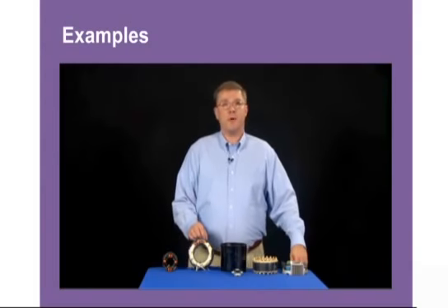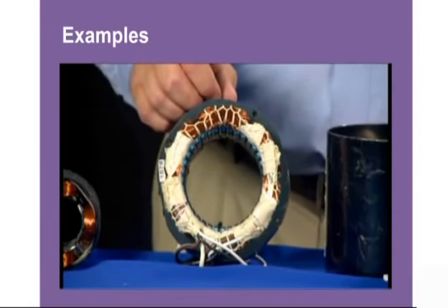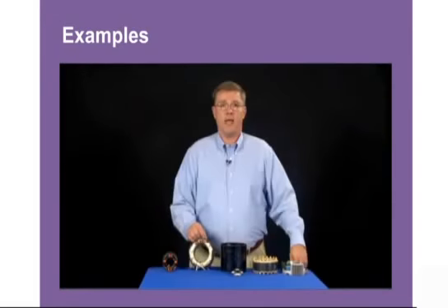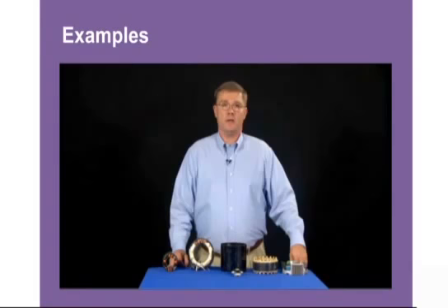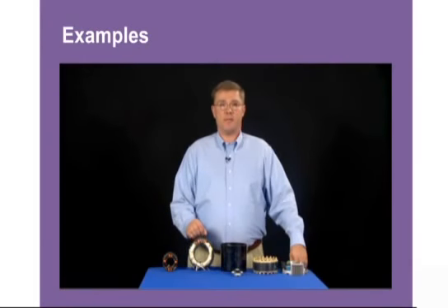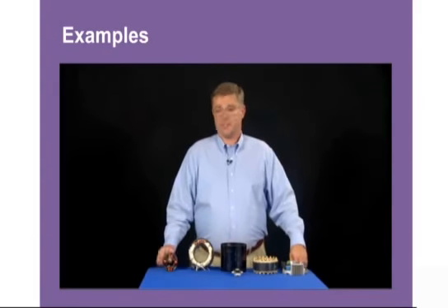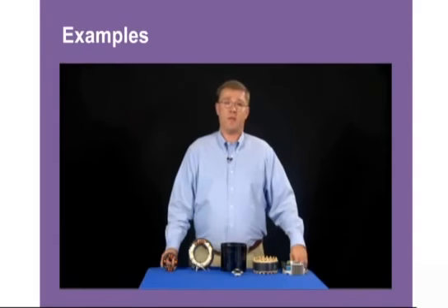The next type is a permanent split capacitor motor or PSC. This type of motor has 2 sets of windings, an auxiliary start winding and a run winding, and both windings are always in the circuit. Thus, this motor becomes twice as efficient as a shaded pole motor. Anytime it's possible to take a shaded pole motor out and replace it with a PSC, you should try and do it. How we do that is a 6 amp motor that's shaded pole, we cut the amps in half and replace it with a 3 amp PSC.